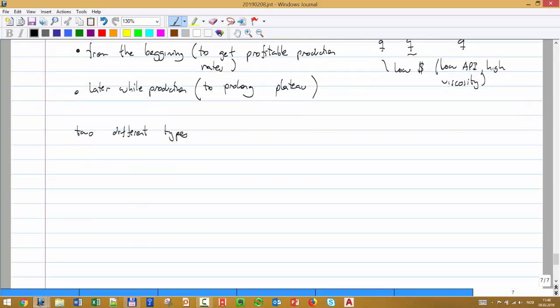I can apply it on a well level, and this is what we call artificial lift. Or we can apply it on a system level, and here is typically where we have boosting. In well level, we serve one well separately. This component will be simply for one well, and in a system level, we do it for a group of wells.